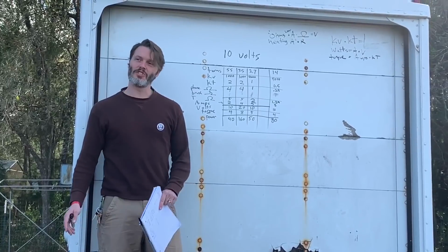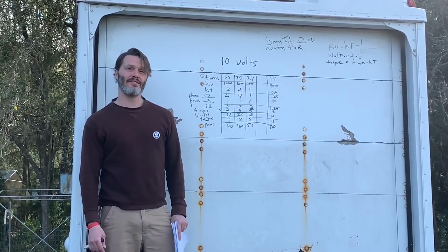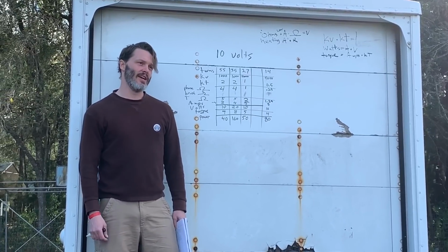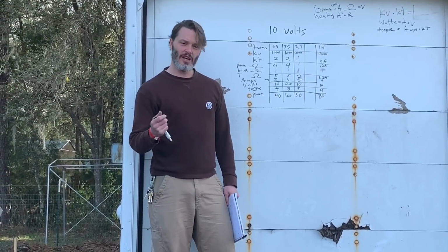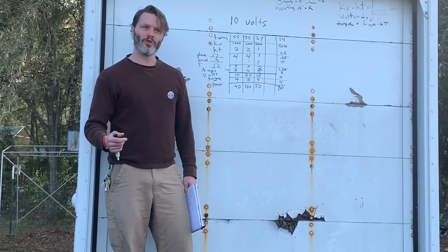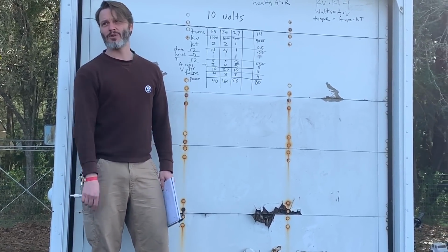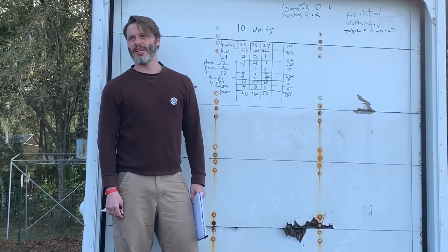So really the moral of this story is that you can't go too fast, even in a crawler system with a ton of gear down, because your ESC will not like it. It'll overheat long term on the trail. You get what I consider a soft throttle feel. You'll lose drag brake, you'll lose torque. And over the long term, if you're on the trail for a couple of hours at a time, it's just not going to be happy. It's not going to work out.